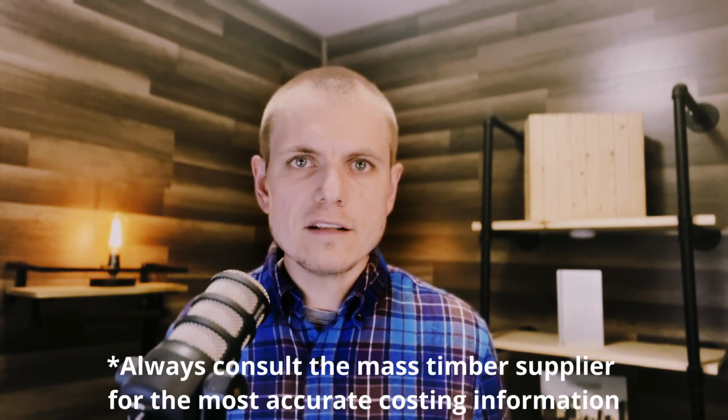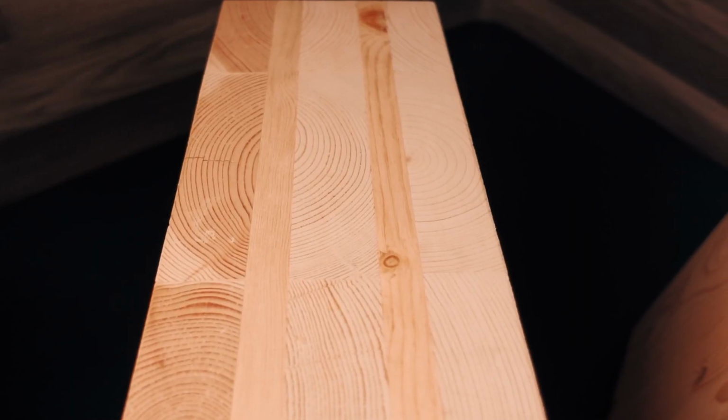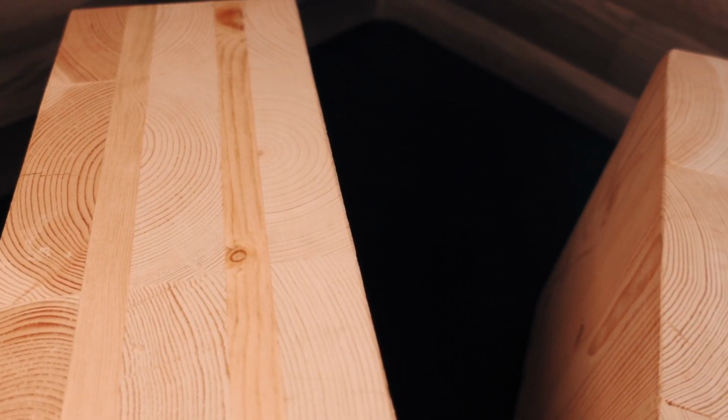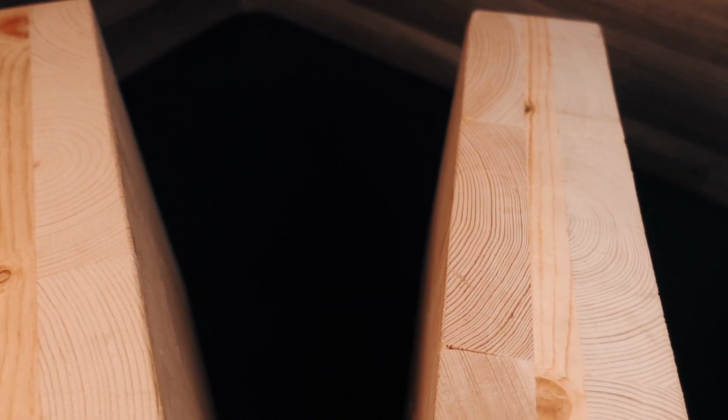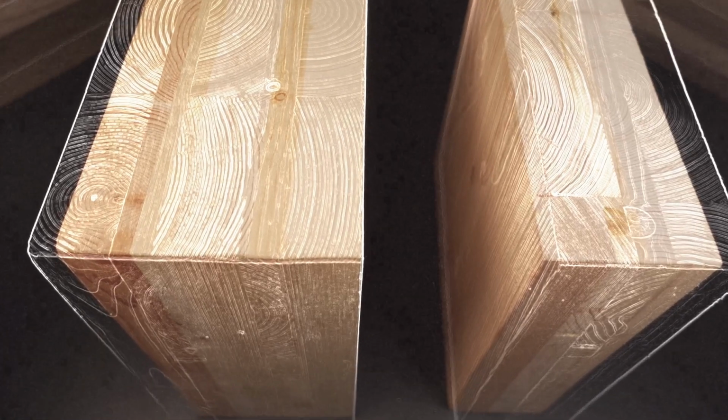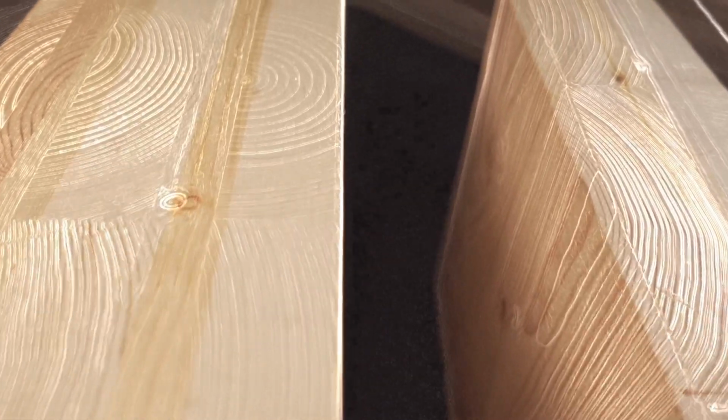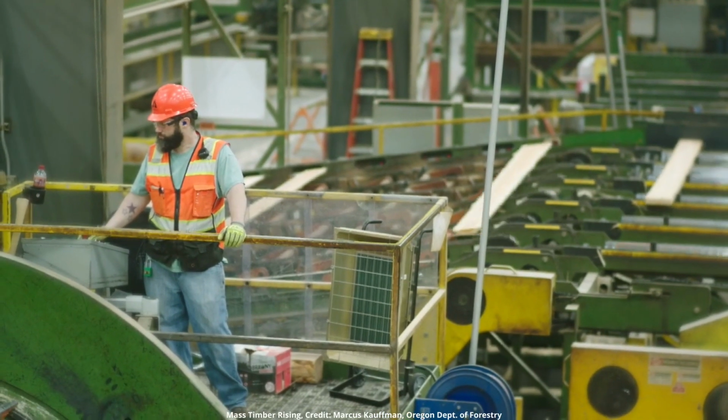And then lastly, an example where the volume and unit cost really tie in together is something like panel products where maybe we're using laminations of varying thicknesses. For example, some manufacturers produce a 3-ply panel or a 5-ply panel where perhaps the strong axis or major axis laminations are of a certain thickness, maybe they're 1 3/8, and then the weak axis or minor axis laminations are a thinner lamination, a thinner layup. So that can be more efficient in terms of material use, right? That draws down the volume of timber used, but it may be a little bit less efficient for them to fabricate because they're pulling from 2 different lamination piles in order to create that panel.